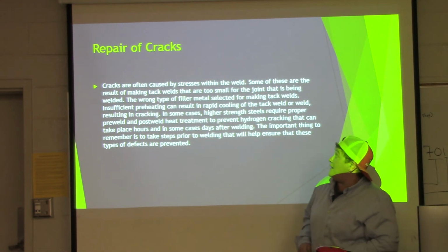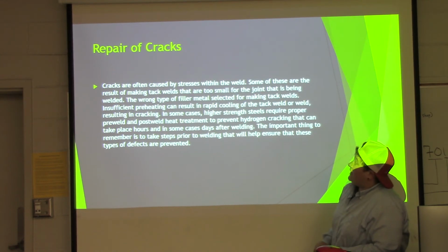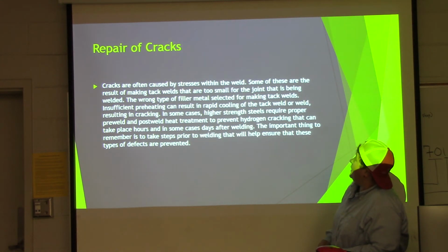Repair of cracks. Cracks are often caused by stresses within the weld. Some of these are the result of making tack welds that are too small for the joint that is being welded, or the wrong type of filler metal selected for making tack welds. Insufficient preheating can result in rapid cooling of the tack welds or weld, resulting in cracking.